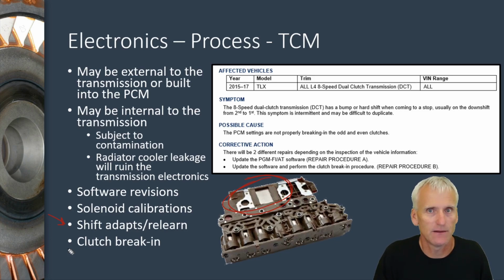Now if you replace that part and you don't reset and relearn this stuff, it doesn't know that there is anything different, so it's going to operate it still with that failure in mind. And now that failure has been addressed, and you're going to end up having a hard shift or slipping gear or something like that. So those are things that you need to be aware of.